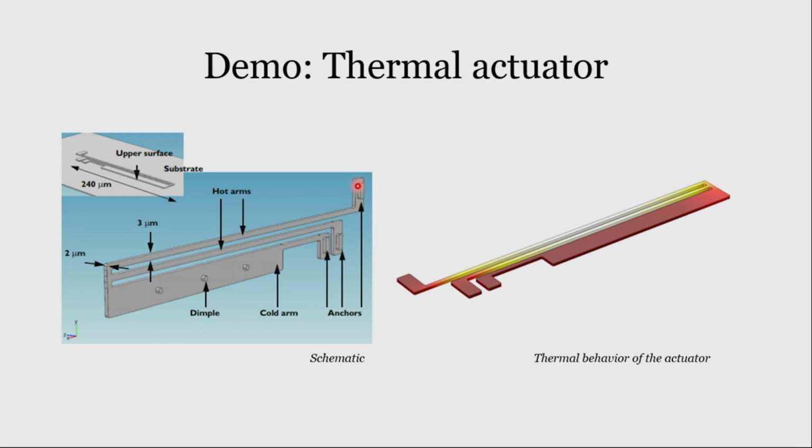So the flow of current will actually be from here, it will go like this, and then it will be divided into 2 parts over here in the second from the top, and from the third, that is the cold arm over here. So the current will be getting divided into 2 arms, and most of the heat energy that would be dissipated would be in the top arm that you can see over here. The heat which is getting dissipated will also lead to thermal expansion.